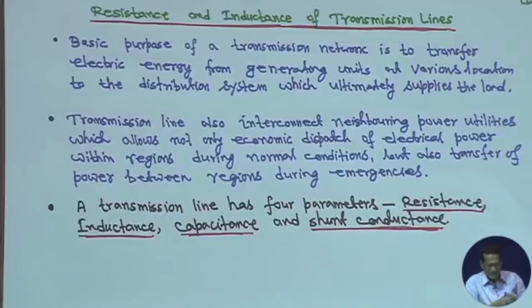Whereas in the case of inductance and hence the reactance, when I was making some computations, I found that the reactance generally, with voltage level from 33 kV to say 400 kV, varies roughly between 0.26 ohm per kilometer to 0.34 or 0.35 ohm per kilometer, right.